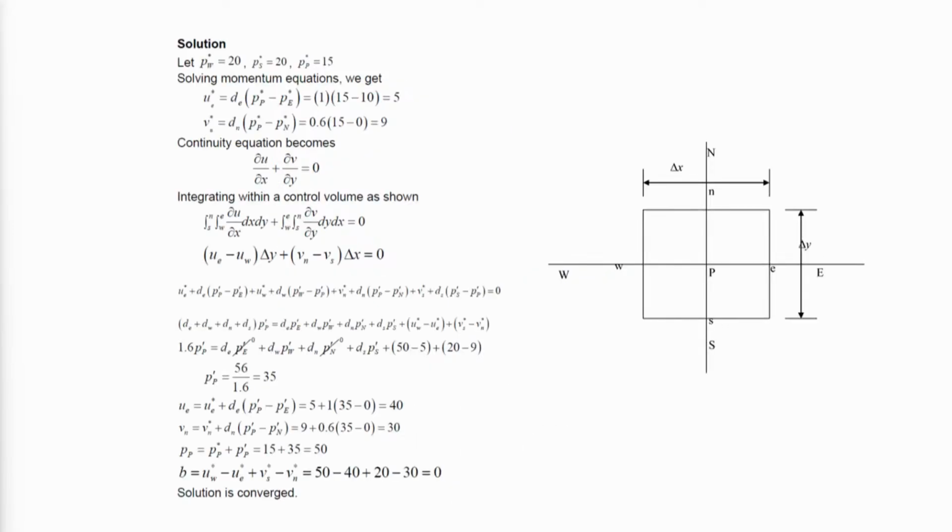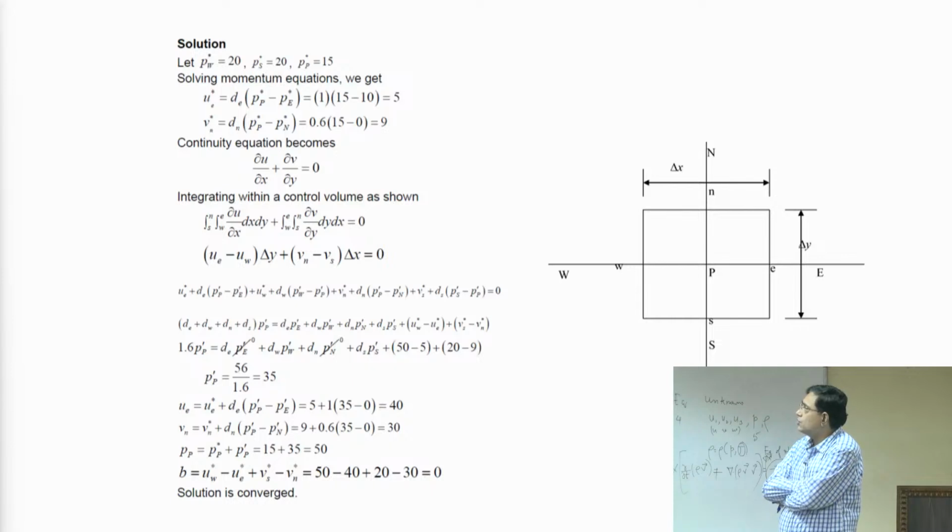So these are actually artificial problems, but these are given to create a concept in you. So wherever this pressure correction is not given you can assume something. So what you can do is you can assume the value of pressure. So once you assume the value of pressure you will get a value of velocity, because your equation is of the form U star is a function of P star. So put a value of P star and you will get a value U star. If P star is not correct, U star is also not correct. That is the central philosophy, very simple.